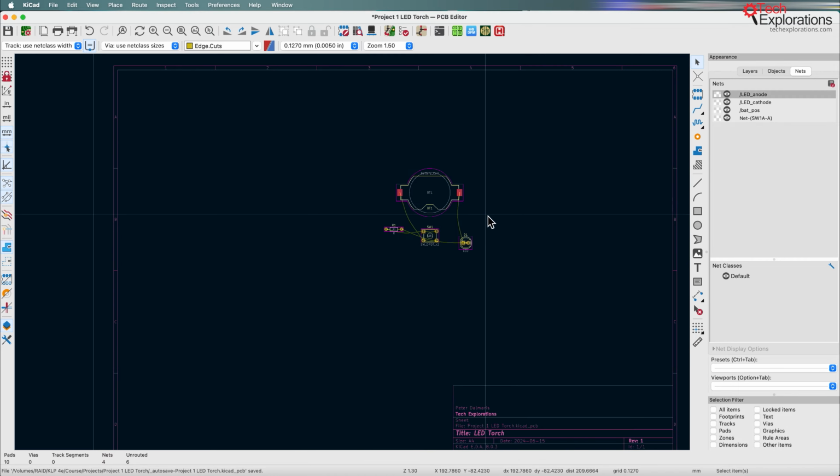To define the geometrical constraints, I ask questions similar to these. For example, how large would I like my LED torch to be? This dictates the board's overall size and cost. How will I turn the LED on and off, which indicates the approximate location of the button or the switch? For example, I might want to turn the LED on and off momentarily with a push button using my thumb, so that will dictate its position relative to the rest of the torch.